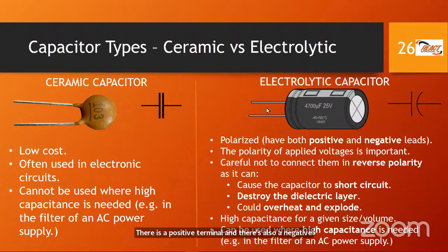It's important when we insert it into a circuit and apply supply voltage to it that we do not reverse polarity or go beyond the reverse polarity that it can handle, because it can damage the capacitor. It can short circuit the capacitor, it may in fact fry the dielectric layer. And if that happens, it can actually overheat, swell, and maybe even explode, right? So that's, again, safety first. We need to be aware of that with electrolytics.